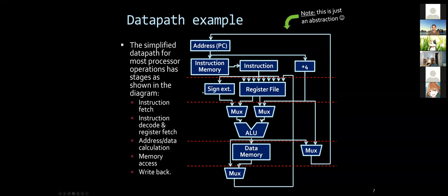After you decode, the instruction uses registers, as we learned in the previous lecture. So we need to understand which registers it uses and get ready to read those registers. We might also need to do something called sign extension. We'll see why this is needed. After we get those registers, we need to mux the values that are needed to the ALU. Remember, the ALU operates on only, say, 2 registers or 1 register, so we need to give the right values to the ALU.